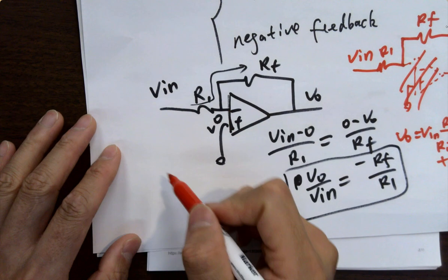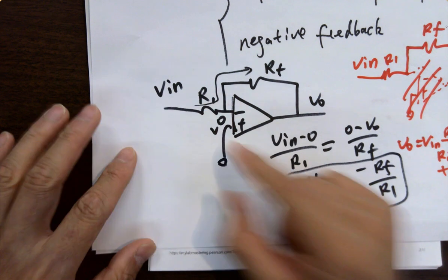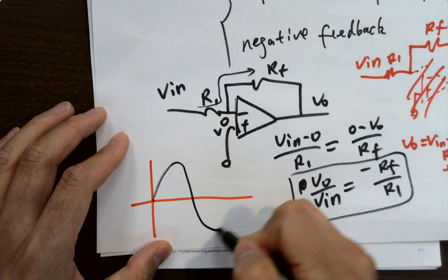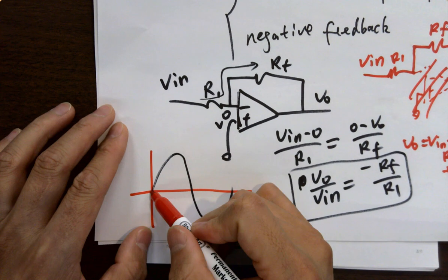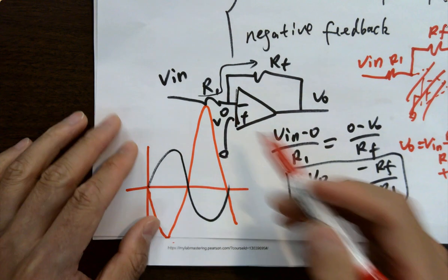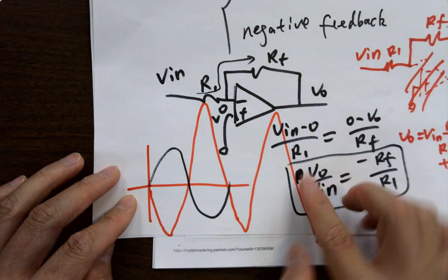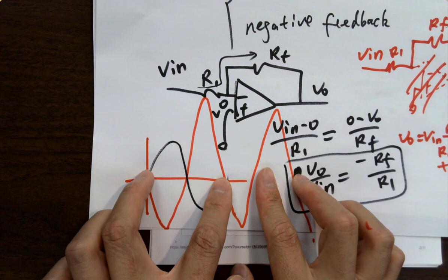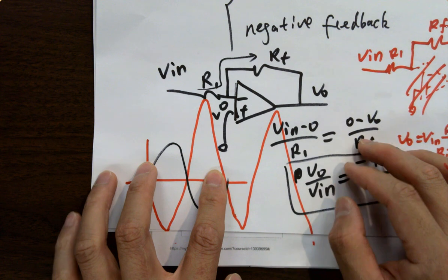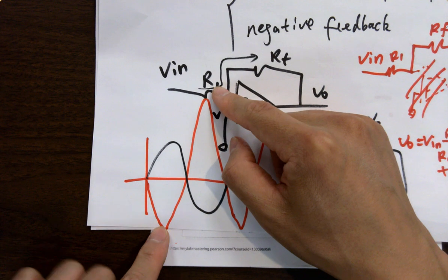Eventually, for this configuration, since you have this op-amp over here holding the voltage, the two voltages are the same. Then your signal, here's the input, and it's being amplified. You are getting an amplified signal like this, even though there is a phase shift. Because this one comes here, it becomes a sine wave again. It seems like the output here is shifting the original signal's phase by 180 degrees. It doesn't matter. You can always invert it back by using another inverting amplifier. But the thing is, you are getting the amplitude amplified, which is the goal.